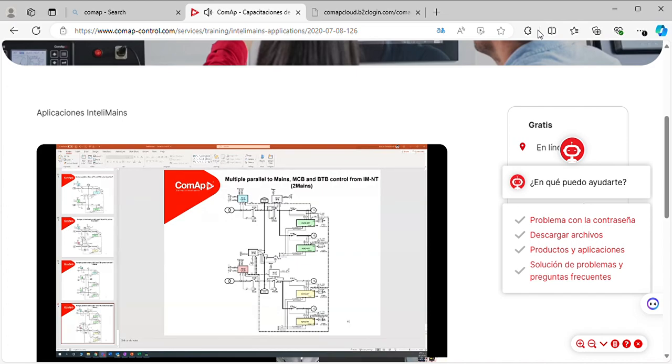Okay, no timers, so I can close the second breaker and I can close this one as well. So now it is trying to synchronize. There is a sync timeout running. Once they have synchronized, they are ready, and I can close the MGCB. So it is feeding the load as well. So they are stable. There is some load sharing happening between them. Once I start loading, they balance out.